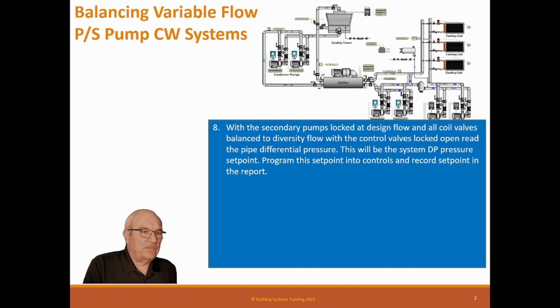The right way is to not have it modulating, and when you're done with the balance, now you know exactly what the set point is because you've got the pumps blocked and you've got the coils blocked, and they match flow. It's perfect. That's the PSI you want to maintain.